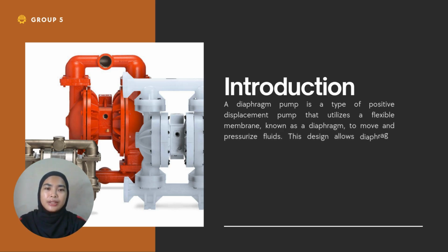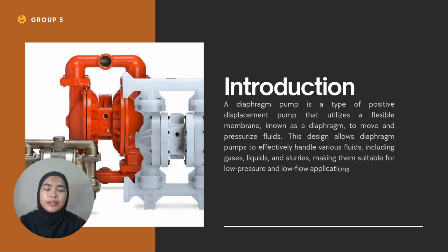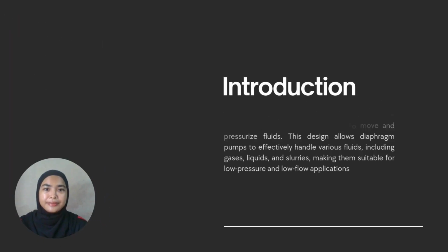So for me, I will present the introduction to the diaphragm pump. A diaphragm pump is a type of positive displacement pump that utilizes a flexible membrane, known as a diaphragm, to move and pressurize fluids. This design allows the diaphragm pump to effectively handle various types of fluids, including gases, liquids, and slurries, making it suitable for low pressure and low flow applications.